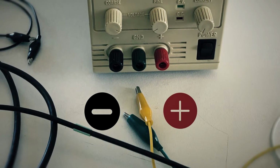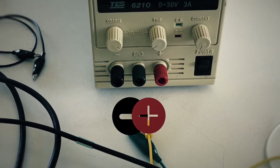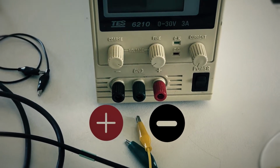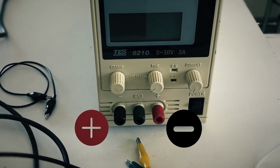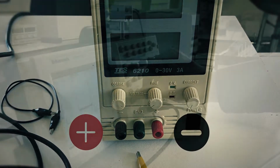A voltage source is also necessary to reverse bias the photodiode. This type of device should always be reverse biased to enhance the already present junction-driven electric field. A stronger electric field will properly separate the electron-hole pairs created by the incident photons and accelerate those free carriers, guiding them to the device's terminals.